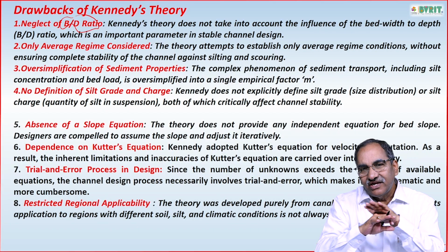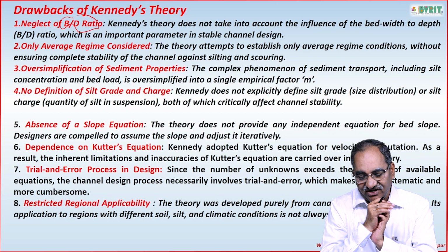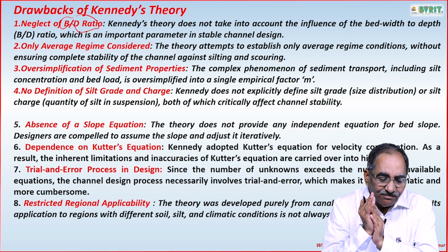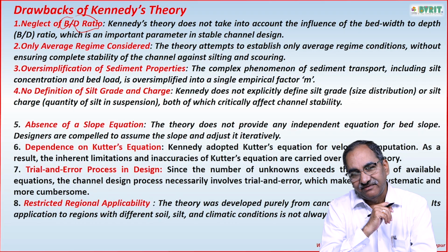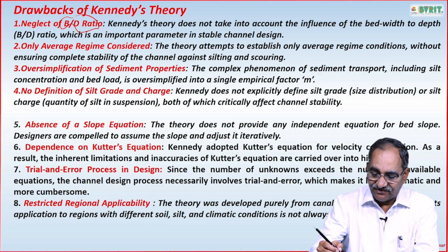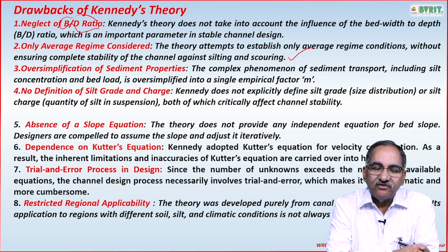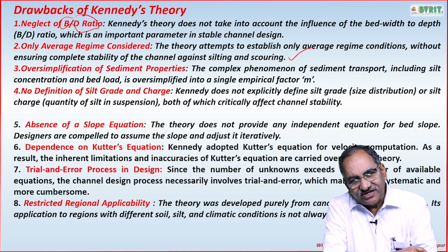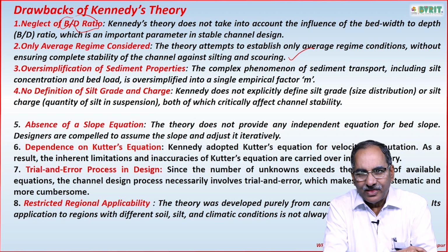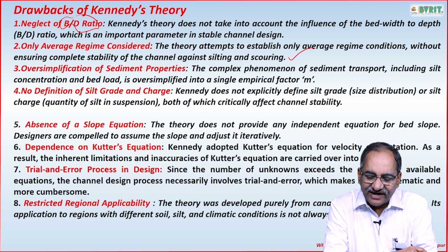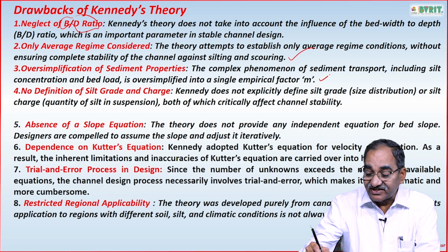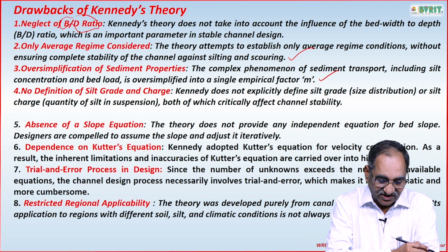That is his first drawback. The second thing is that only average regime conditions are considered. That means he did not ensure the complete stability of the channel against silting and scouring. That is number 2. The third one is oversimplification of sediment properties. The entire sediment property he has taken is only the critical velocity ratio. That is the only thing through which he explained the entire theory, so to what extent that validity holds is a question.